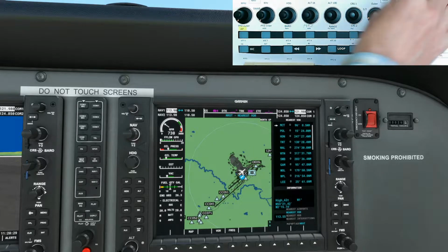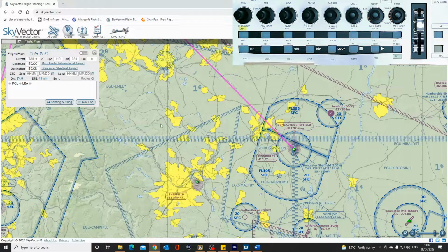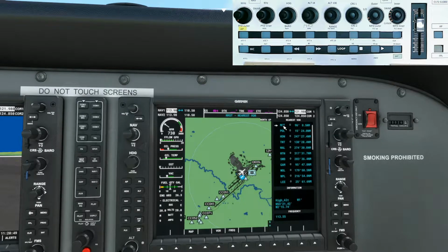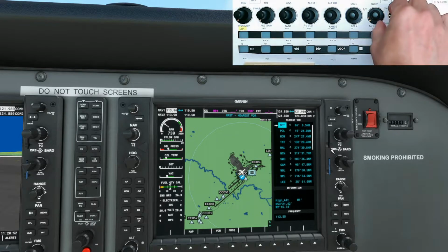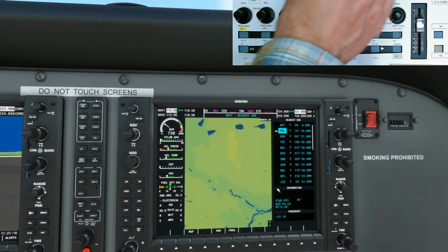There's our nearest VOR. And if you remember back in our flight plan, there's Pole Hill, and on the chart here it says the frequency is 112.1, and if you wanted to find that here, bring up the cursor down to Pole Hill and it agrees here, and it's 24 nautical miles away. 15 degrees is the direction we need to go in. Now I haven't found any way yet of bringing that up here. If there is, I'd love to know how to do it.